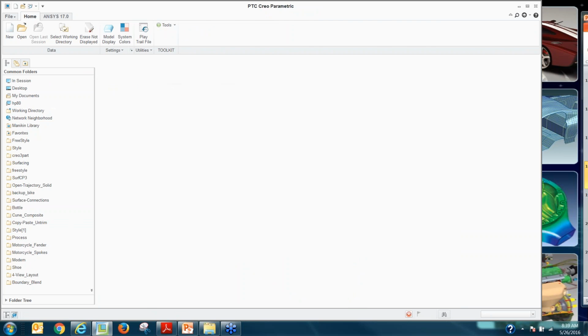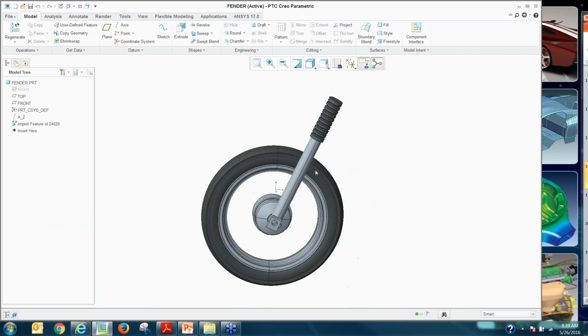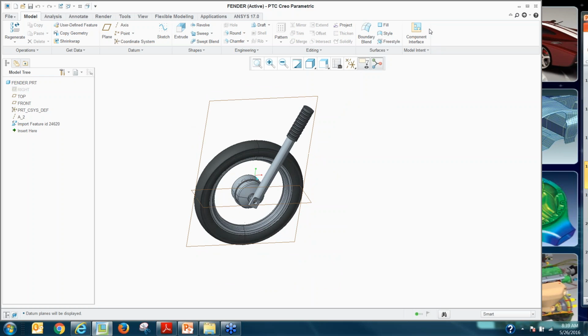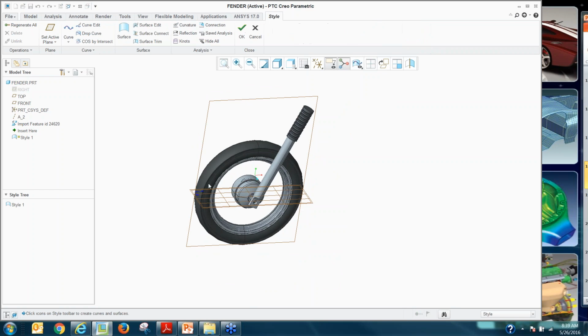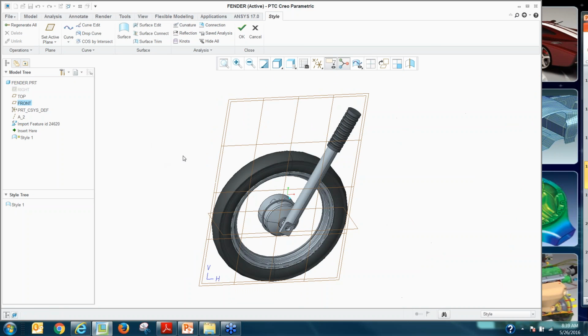designs. For example, let's say that's something that was already done. Let's say I need to build the fender for this component somewhere around here, right? So maybe I want to start, instead of using my technical surfacing, I'll show you the flexibility with which you're able to use style. When I go to style, and when I start creating my curve, I first set an active plane, just kind of like your sketching plane, right? Pretty much the same. And you see, it's very intuitive, right?